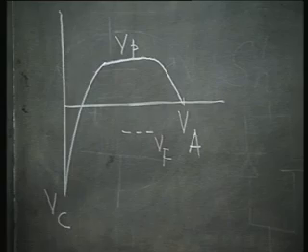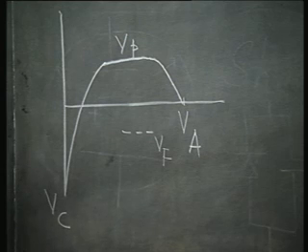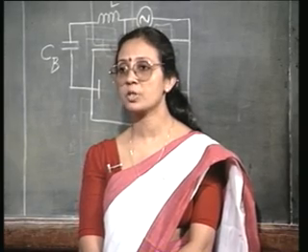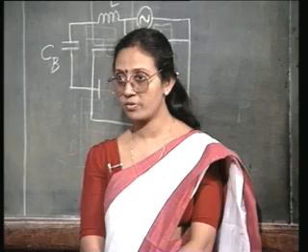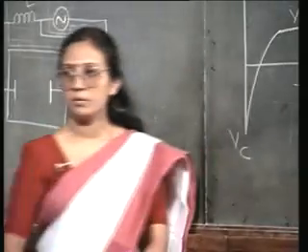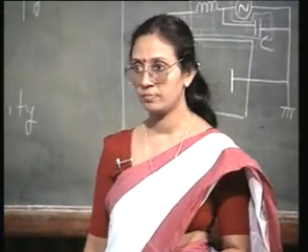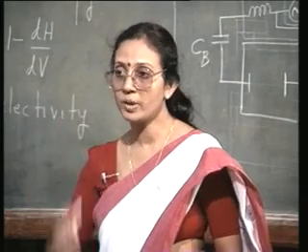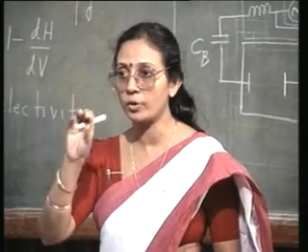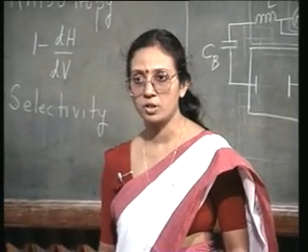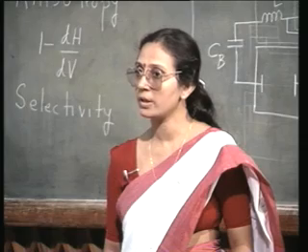So, you see, the ion bombardment energy will be directly proportional to the voltage difference between the plasma potential Vp and that particular surface. The plasma potential is the center. So, with respect to that center glow potential, if the surface is at a much lower or much higher potential, accordingly the ion bombardment energy will vary.